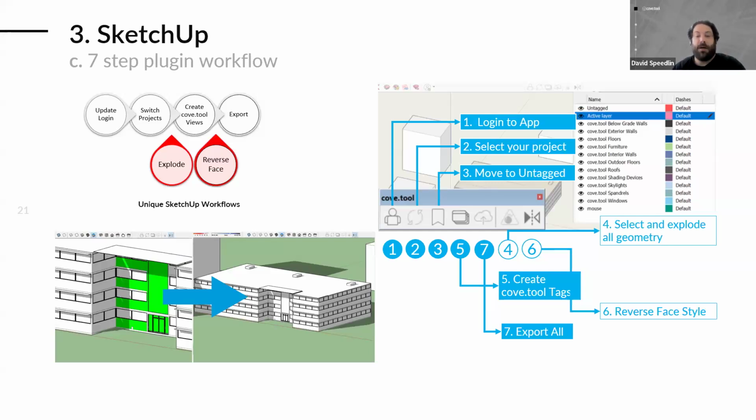One of the new buttons that's here for use is the flipping a reverse face. One important part of SketchUp is that it has a front and a back face. So you want to use the flip face button tool so that you can see a view where it's highly contrasting colors, and you're able to figure out which surface should be facing exterior, which surface should be facing up. It's crucial that exterior walls and windows display the front-facing surface outwards, and roof geometry have their front planes facing upwards, while floors have their front planes facing downwards.